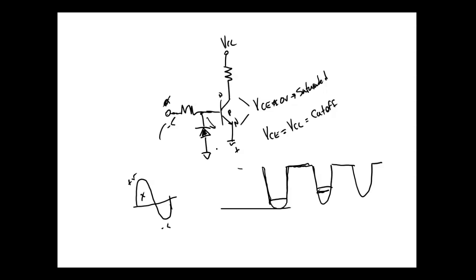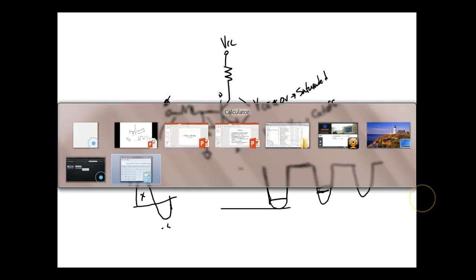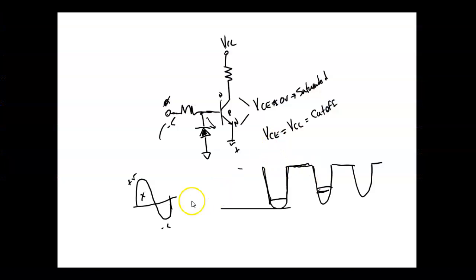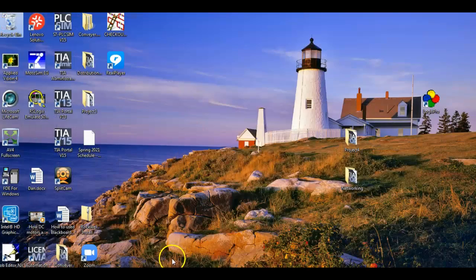Now why would I do that? Why would I put that diode in? Huh? Well, it's not a zener, it's a diode. It's not a regulator. So when this goes negative, it's going to forward bias it, and the entire voltage will be dropped across that resistor except for negative 7/10 volt. So on transistors, the base junction is not designed to be reversed. The base emitter junction is not designed to be reverse biased.